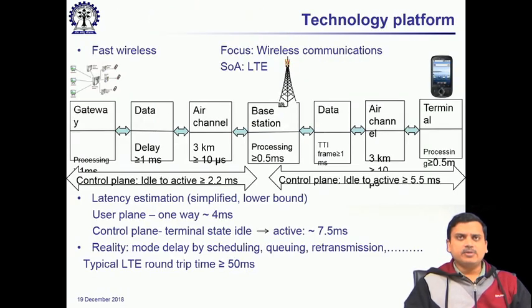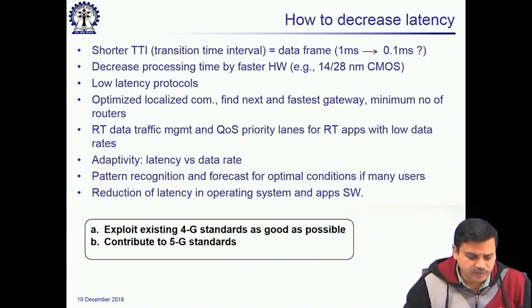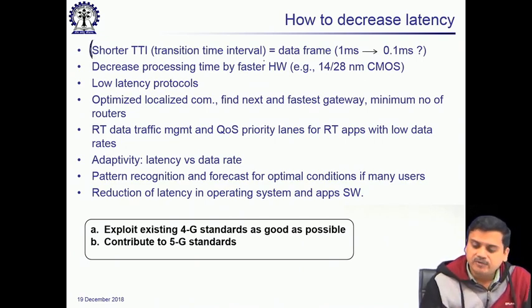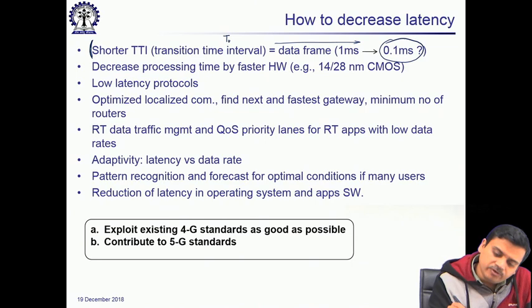We have already established that low latency is a very important case, and we have also discussed how things have happened. Amongst the various things, what has played a very important role is the short TTI, that means transmission time interval, which is reduced, right, and then the next question is, can it be made even smaller. The moment you reduce the transmission time interval, what we find is that OFDM symbol duration decreases, as a result of which the subcarrier spacing increases.